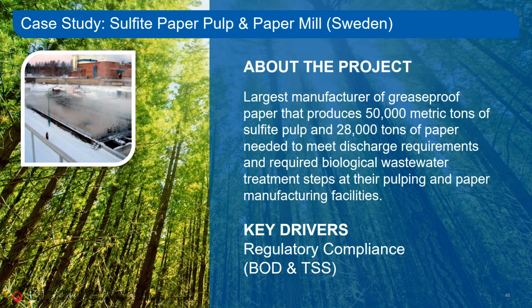The other one is maybe not a very typical production because it's a little bit special. It's a grease-proof paper, but just to show how we can use this technology in a very flexible way. And this mill needed to meet discharge requirements that required biological treatment. Then we looked into the situation, and they had rather big clarification basins. So part of that was rebuilt into MBBR reactors to treat all their wastewaters biologically, and then use part of the clarifiers for separation after MBBR. You can see the next slide.